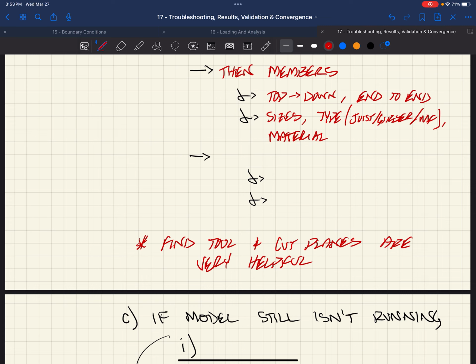But if you had 2 different beams, right, now all of a sudden it does play a role as to the stiffness, right? And so you just have to be careful about that a little bit, making sure that you don't have an influence of stiffness that's going to dictate, how steep is that line in our stress-strain diagram that gives us our strain energy, right? Are we going to change the amount of strain energy? Then lastly, I do plates.